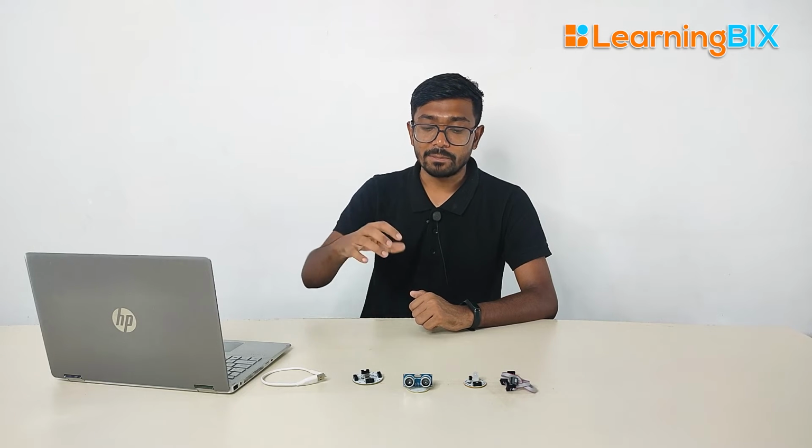So I am calling it by the name MyBot. Now after that, let's go to your setup file. In the setup file, we write the code that will execute only once. That is the initialization. For example, I am initializing this ultrasonic sensor. I am initializing this RGB. So whatever objects you want to initialize or run once, you have to write the code in setup.